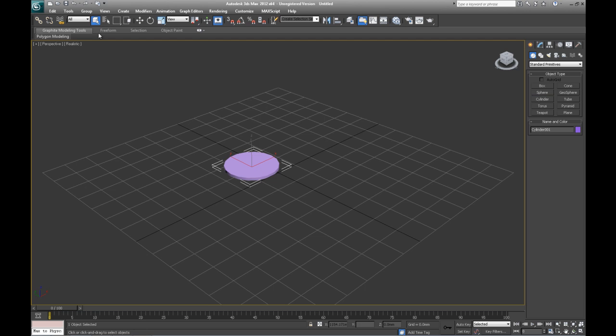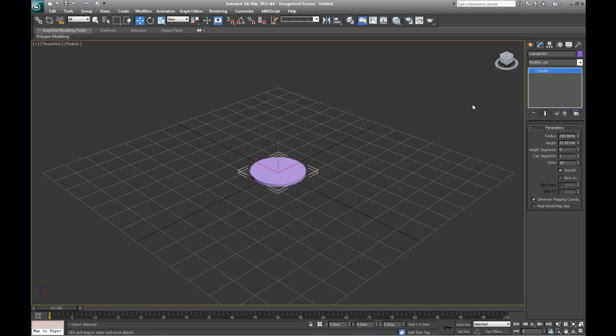And what I'm going to do is select that using the selection tool here and just set its X and Y coordinates. Let's make it on move, sorry. And we're just going to set it to 0, 0 and 0. So that's that. And let's go to the modifier here where we can modify our shape. Let's give it a radius of about, let's see, that's quite a lot there. That's 300 millimeters, so that's about 30 centimeters. Actually, let's give it a radius of about 500, so it's about half a meter in its full radius. That should be about fine there.